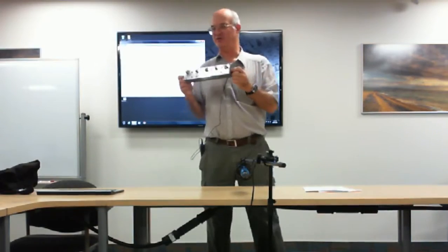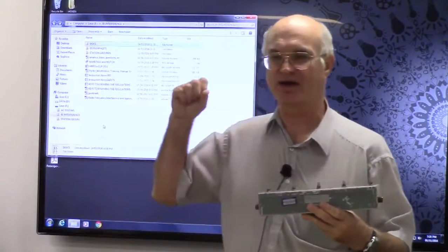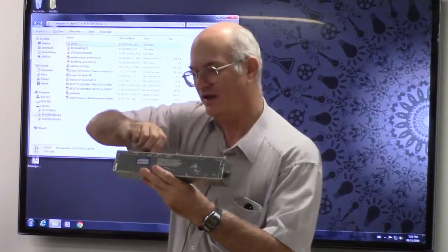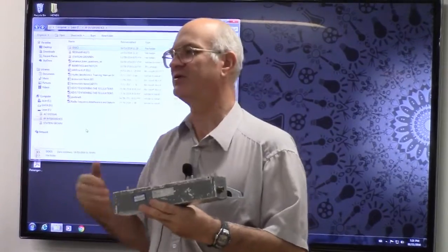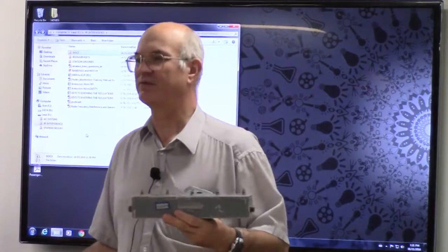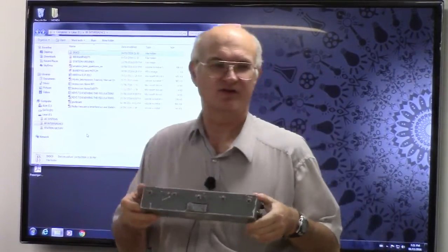Some of these are tunable, so you can actually fine-tune them to get rid of a certain frequency that is irritating you. This one here is a more advanced version. This one actually can be tuned for each band. So if you had a particular harmonic that was right next to your neighbor and bugging his favorite TV channel, you could literally go to the right one and shift it a couple of megahertz. Even though you couldn't get it down to the level that it wouldn't bother another receiver, if that frequency is not being used, your problem is solved. So these are a little more advanced.